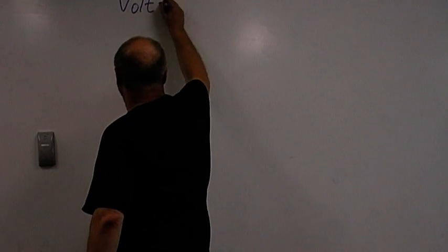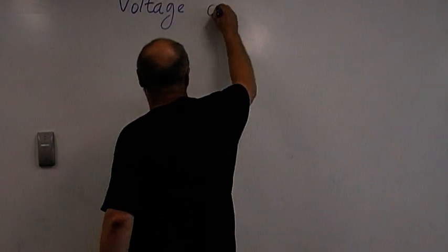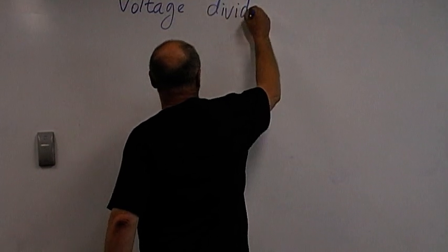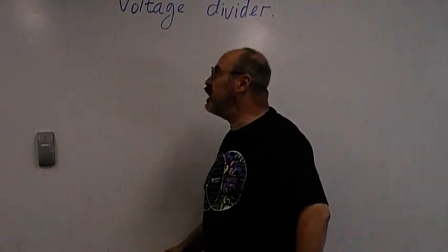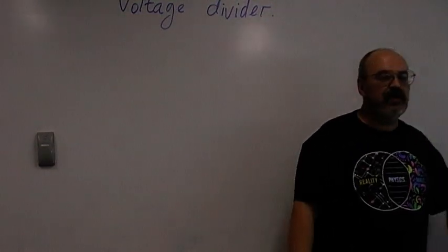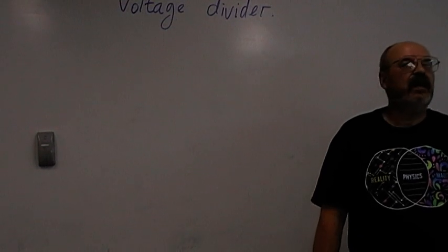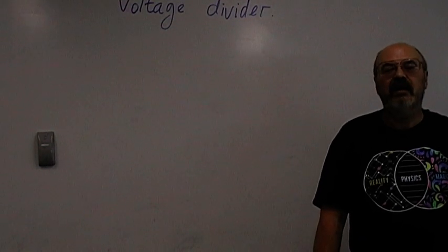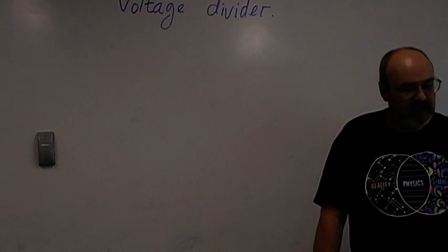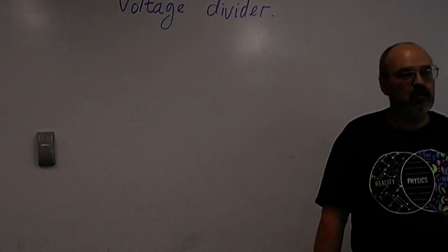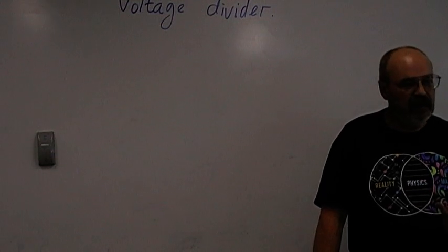Now, a very important application of the series connection is the so-called voltage divider. If you have, for example, a power source providing, let's say, 20 volts, but you require 5 volts or something, we can use a voltage divider to get the voltage you need.